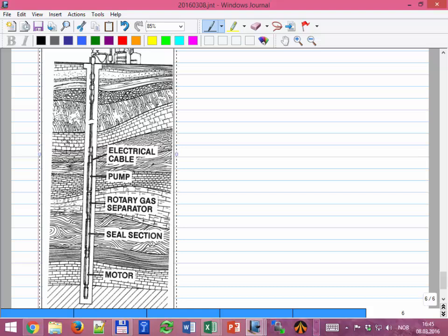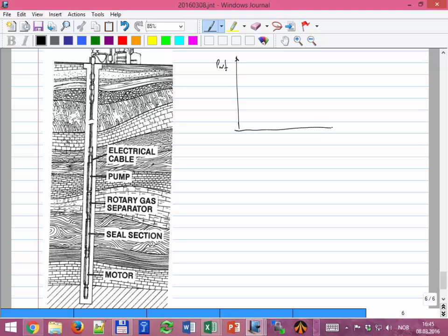Okay? And you already have some idea that if I do my equilibrium, let's say at the bottom hole pressure, I have a Q of oil, and then I have the available and the required. If I want to be producing here, then I have to put something that bridges that difference. It's just like the choke, but the opposite of the choke. I want to put in the pump, which is going to bridge and give me this delta P.